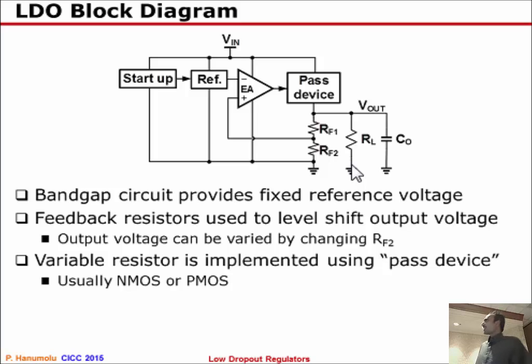If you take a much closer look at these LDOs, what you find is the following. You have the feedback network shown here, which consists of an error amplifier, because it's going to measure the error between the desired or reference voltage and the fraction of the output voltage, and it's going to regulate a pass device. Previously, I showed this pass device as a simple variable resistor, but as we will see shortly, it could be either an NMOS, PMOS, or NPN, PNP.